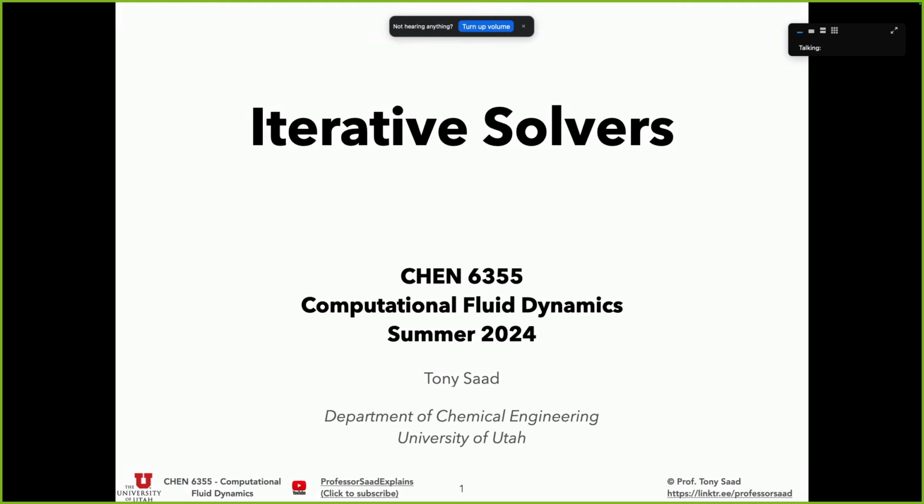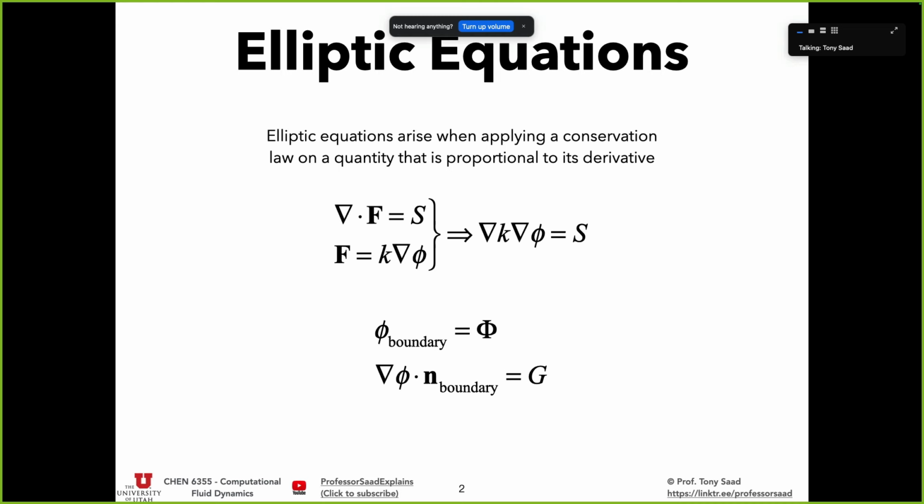Okay. I will start with the problem that we're familiar with when we interacted with linear systems of equations, and that's the Poisson equation. So either steady state heat transfer, which was the 1D heat transfer problem we did at the beginning on the rod, or the Poisson equation for the pressure in 2 dimensions, right? They're just the same problem, but in 1D or 2D, and we're going to extend it to 3D today. That's one example where we recovered a linear system of equations.